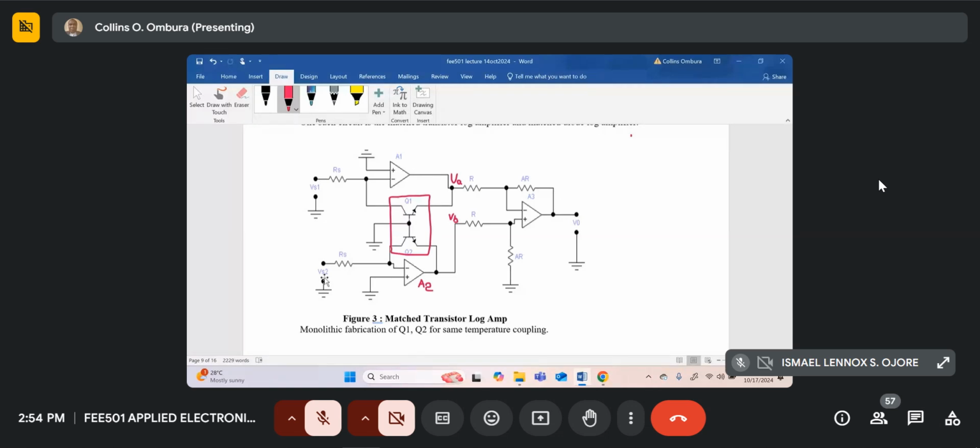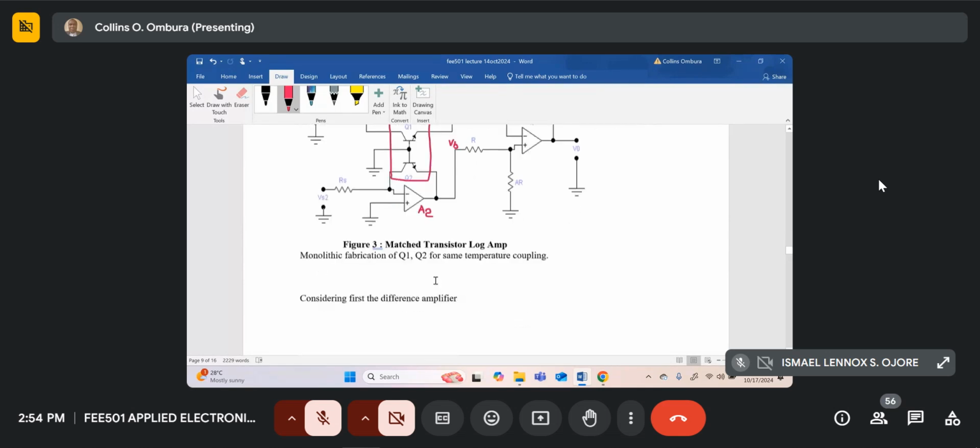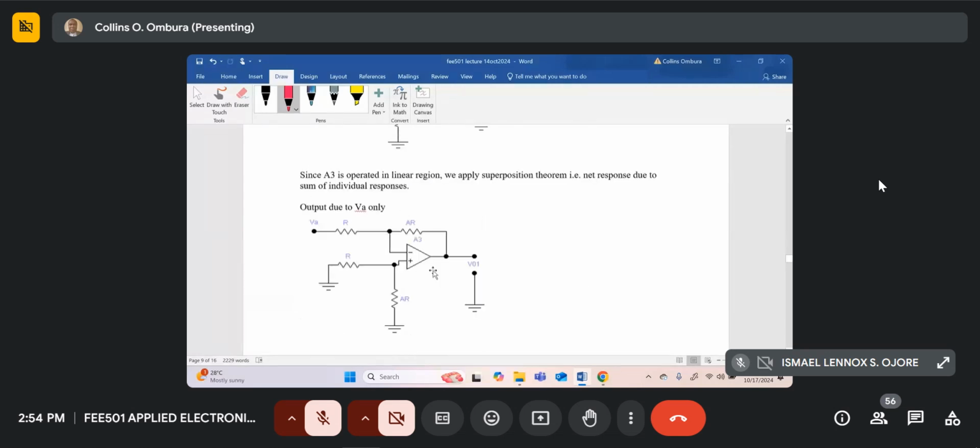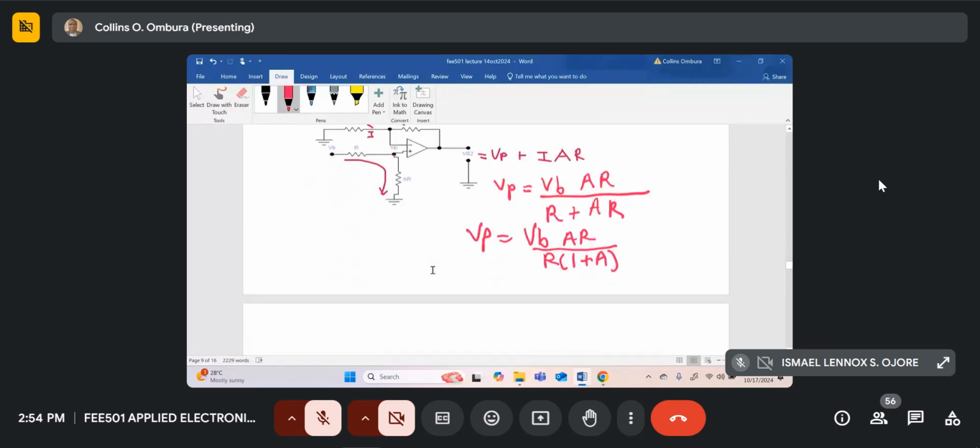The theory is good, but in practice, if you use this circuit, you want to get correct answers. The reason is that op-amps, because of the offset voltages, you have to use null offsetting circuits inside the op-amp for you to get the correct answer. And this is why I was wondering if you are getting correct results in the lab. So all these are not practical circuits you can do in the lab. Now, the practical circuit that you can do in the lab is this next circuit over here.